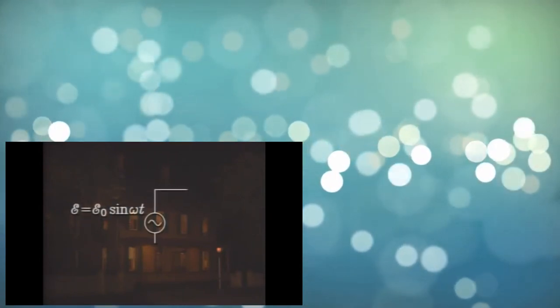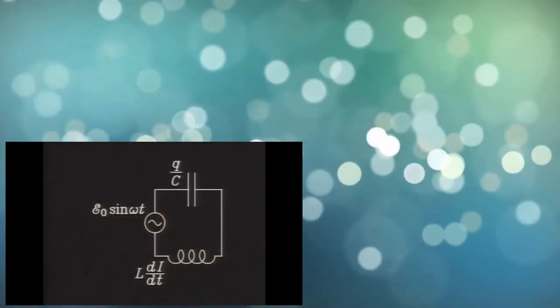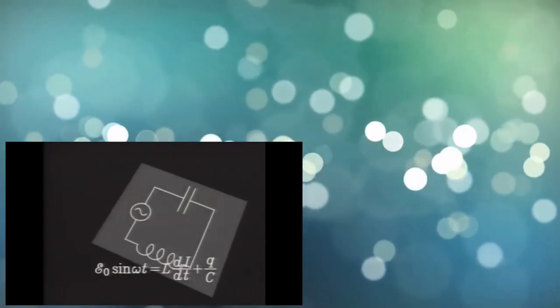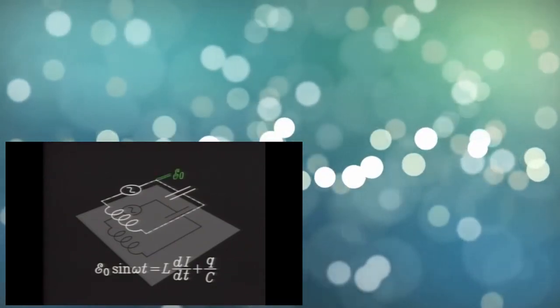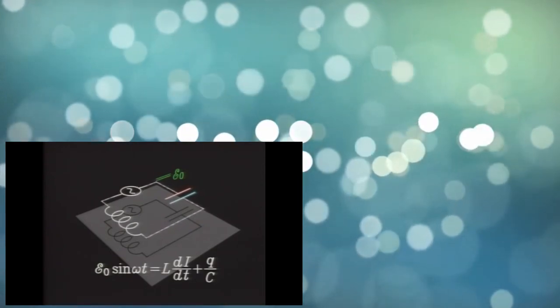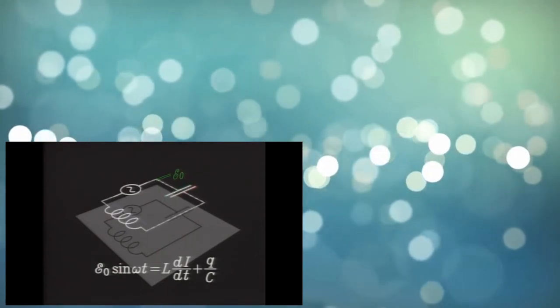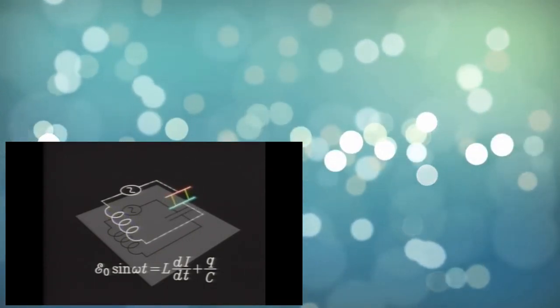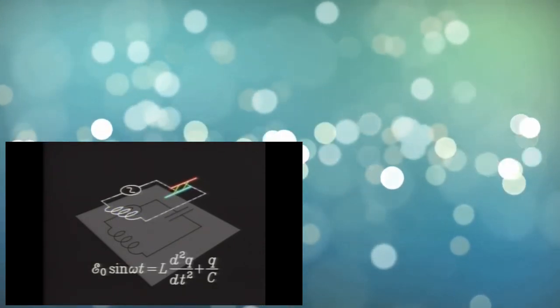Consider a simple circuit that consists of an alternating voltage source, a capacitor, and an inductor. According to the mathematical rules of Gustav Kirchhoff, the rise in voltage at the source, never bigger than E sub 0, is equal to the sum of the voltage drops around the circuit. The result is a differential equation that can be written in terms of the charge Q on the capacitor.